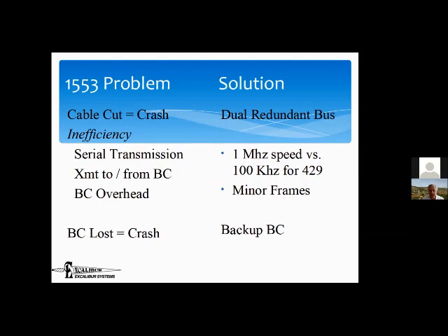Now, redundancy, right now I'm talking redundancy at the communication level. So there's no such thing as only one wire, and we'll see what this looks like physically later on. But the idea is that every box has 2 wires coming out of it. We'll call them bus A and bus B, and they work in parallel, so that if something goes wrong with bus A for whatever reason, we still have bus B available.